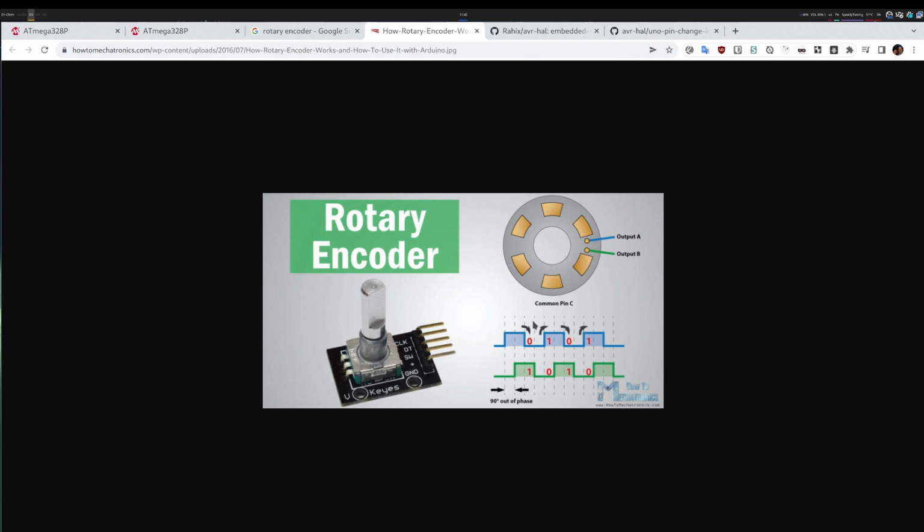So this is how I can detect that I turn towards the right: the clock value changes, I compare the two values, one is high and one is low, and this means I just turned something towards the right. If I go the other way, green will go high first, and by the time blue goes high, green is already high, so they are in phase. This means when I turn towards the left, when my clock changes, both values would be the same value.